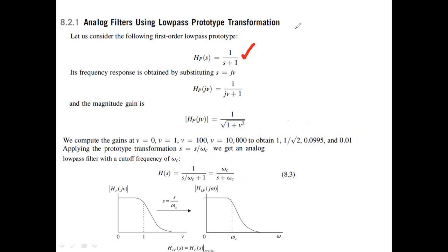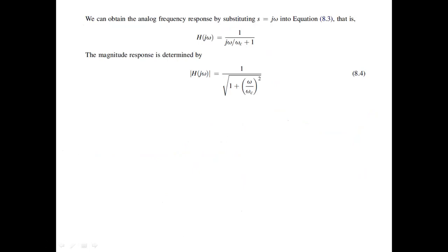So that was a simple low pass first order filter. What about the frequency response? You need the frequency response: you replace S by j omega, then you are ready to substitute and plot it. You just go on changing the frequency, so your x-axis will be omega. At omega equal to 0, you are going to get 1. Then slowly you get whatever shape you want.